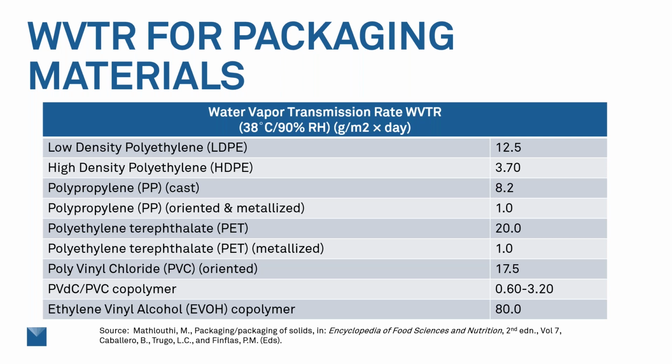I wanted to point out a few things before I go over the table that's important to know. For these water vapor transmission rates, they were done at 38C and 90% relative humidity. That's not always the case, and it's important to know because that's part of the calculation. Sometimes they're, let's say, 30C and 75% relative humidity, but that's part of the definition, like I said, of actually calculating this water vapor transmission rate.